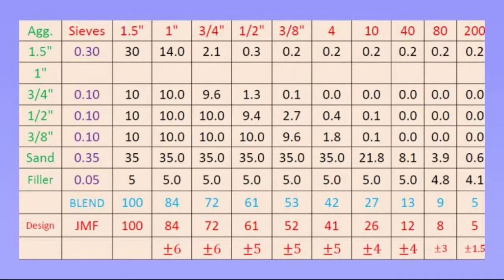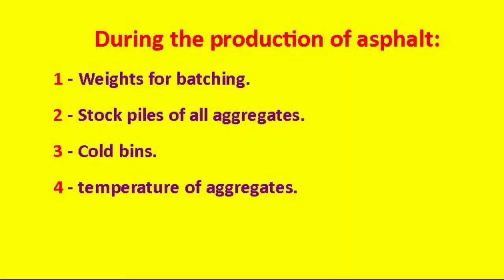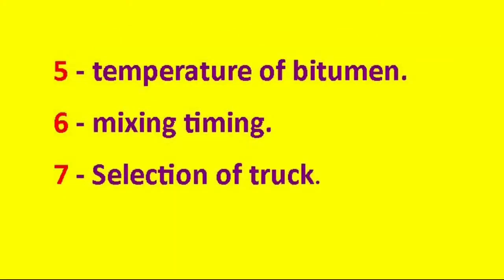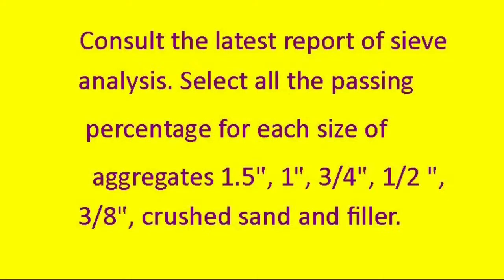Let's start. During the production of asphalt, you need the weights for batching, the stockpiles of all aggregates, cold bins, temperature of aggregates, temperature of bitumen, mixing timing, and selection of trucks. Consult the latest report of sieve analysis.